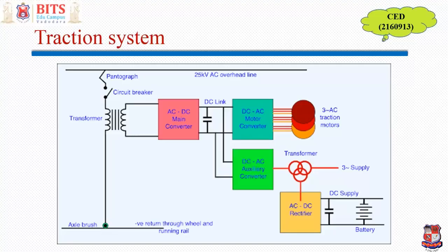That means there's a 40-meter dead zone between two substations, because if one section is under, say, R phase, the adjoining substation will be supplying with the Y phase to have overall three-phase balance. And so two sections have a dead zone or neutral zone between them, which is generally of 40-meter dimension, so that different phase wires are not connected together.